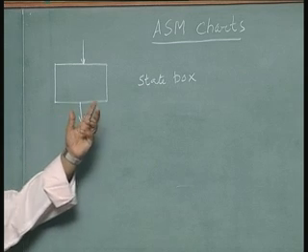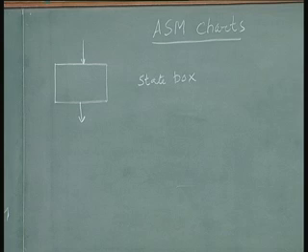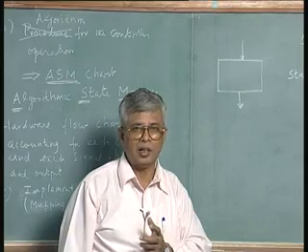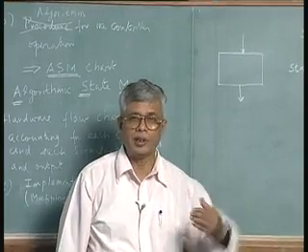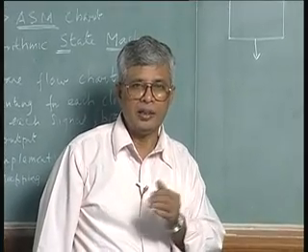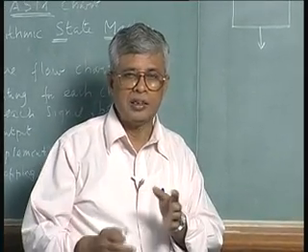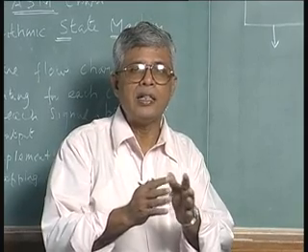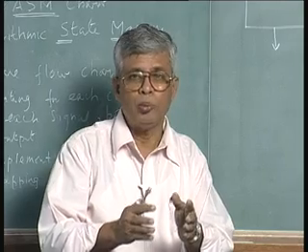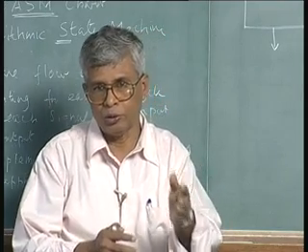This represents the state, as we understand, because in a state graph you know that at each clock cycle the circuit or the system resides in a particular state, and in the next clock cycle the circuit can change to another state or continue to remain in the same state. But you define a state, in a state graph or in a digital system, as the period for which the circuit will not change, nothing will change in terms of its behavior, in terms of the input output. In terms of the output, of course; input you can always change, but it is better to synchronize it.